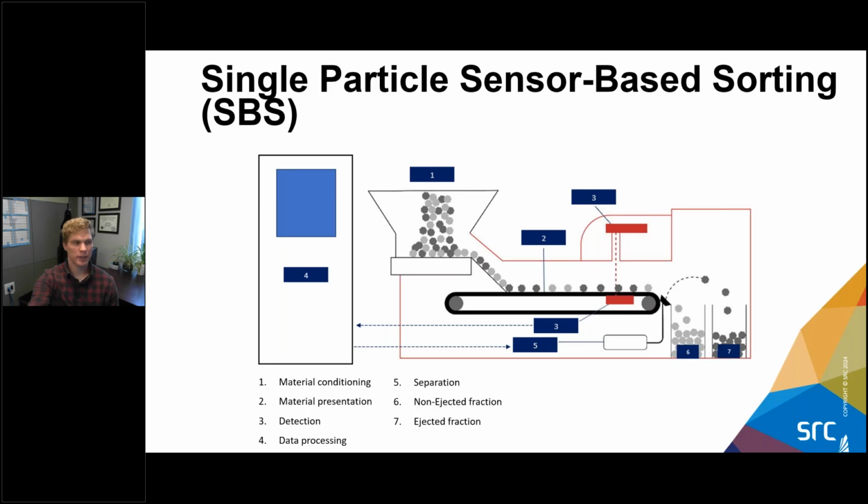But in this scenario, you have a little chute or a little pan feeder that would drop it onto the belt, and then the belt would spread it out in a single monolayer. That's what you're trying to do, a single monolayer where the particles aren't touching, but the belt is as full as it can be. And the reason you want to do that is because if particles are too close or they're overlapping, you could have particle masking. That's also another reason for the 3-to-1 size ratio. It's a lot easier for large particles to cover small particles if there's a big range in sizes. But you want to prevent masking.